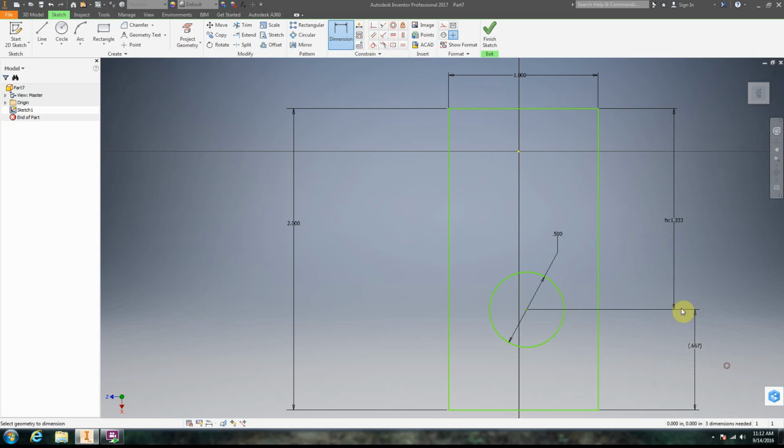So there we're kind of messing around with these dimensions, right? But it's a lot easier than figuring out what some value is. All right, so we have our circle. We also need to dimension it from the side. I'm going to click that. I'm going to click it to the other side, just to lock it in. We accept that it's a driven dimension. See that it's in parentheses. I'm going to click the original one. So we have D5 and we got D6. What I'm going to do in D5 is just put D6, because I want them equal. I hit Enter, and now those two dimensions are the same.